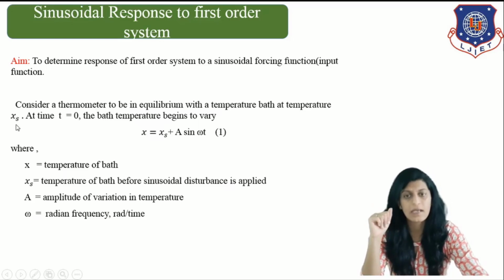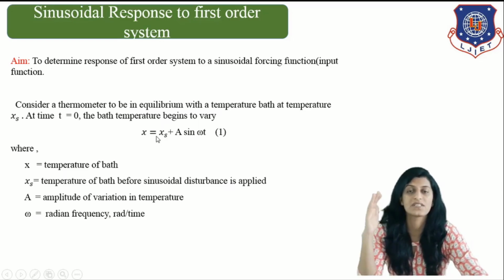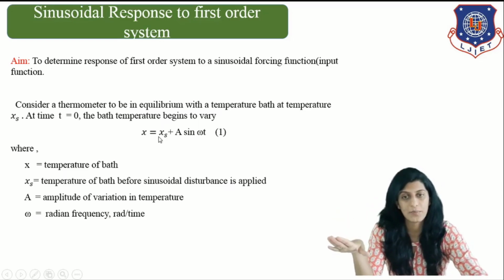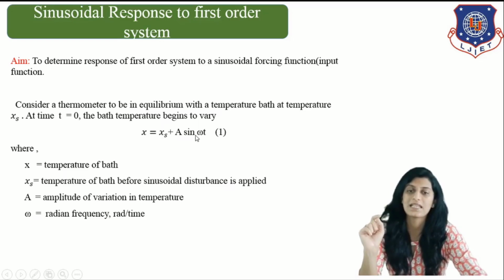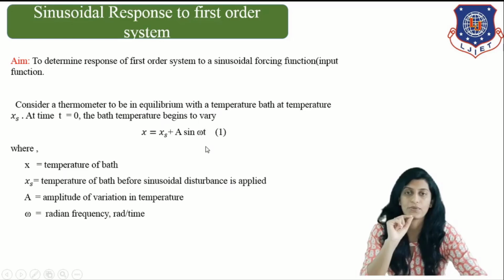So the bath actual temperature, which is the present temperature, X equals Xs, which is the steady state temperature, plus A sin omega t. This represents the sinusoidal input.